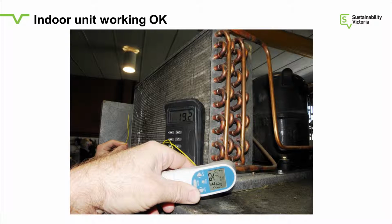Okay, not too warm. And then I measured the point where the liquid comes out of the condenser. So that's kind of the condensing temperature, you could call it that. And I measured that with my little gun. And you can see that was 26 degrees. So the difference between air temperature and condensing temperature was about 7 degrees. That's really good. Okay, the system was running well. 7 degrees is a good TD, temperature difference, as I will explain later.